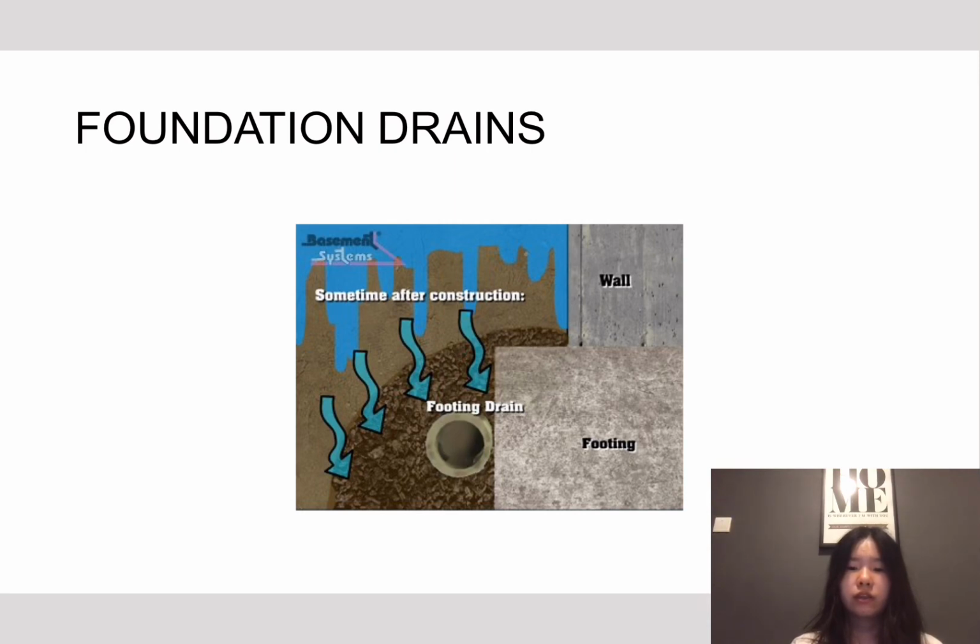Because Malaysia is a country with abundant groundwater resources, although there is no basement and the excavation depth is not deep, it is still very necessary to consider waterproofing. I need not use strap foundation but choose pad foundation plus waterproofing.